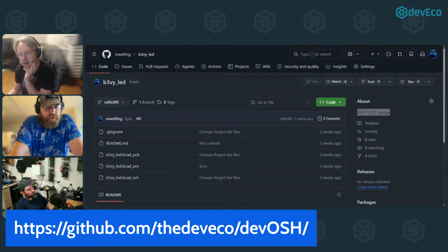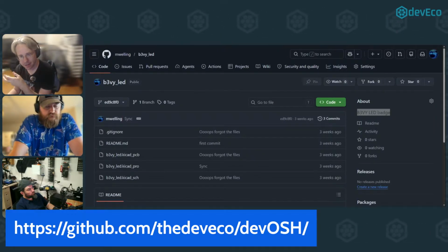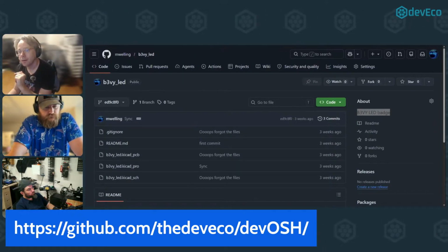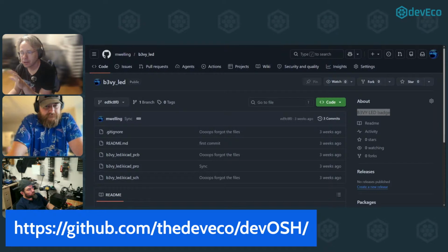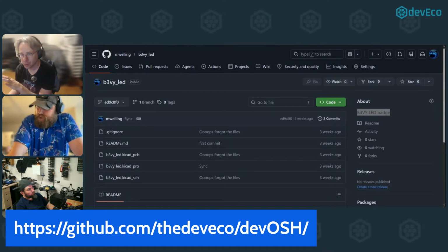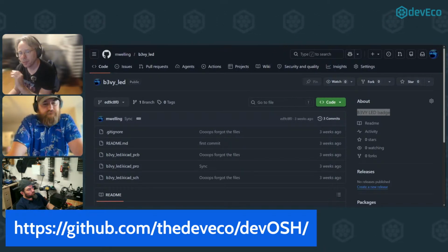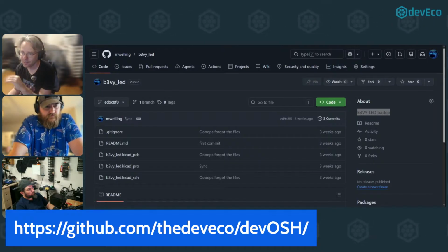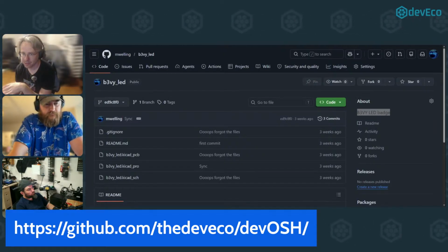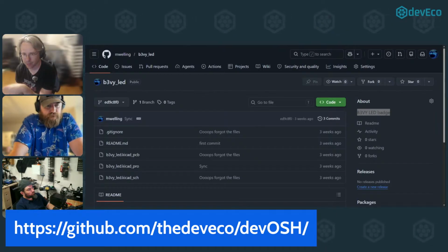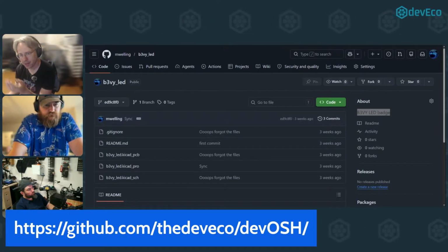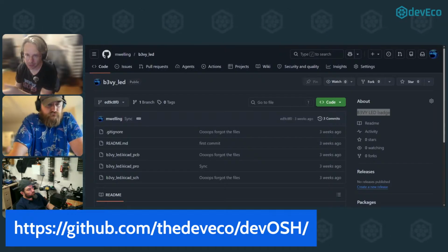All the parts that can be had in Easy EDA are available in KiCad. If you don't have them, you can make them. I think there are LCSC component libraries out there, and I'm pretty sure there's a passive plugin. For a lot of those passives you don't have to do any special component footprints, and a lot of the parts that you can source there, you can source other places.